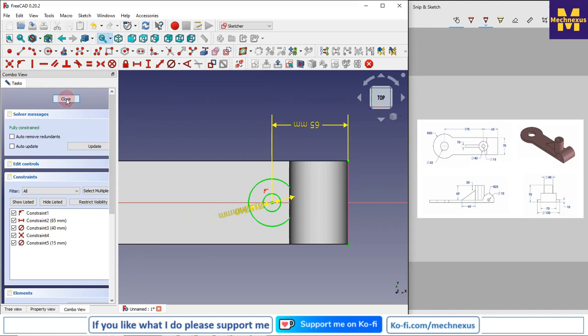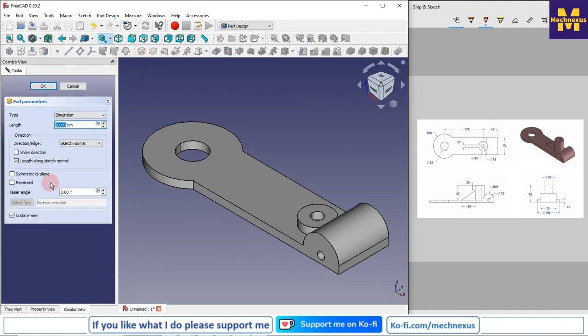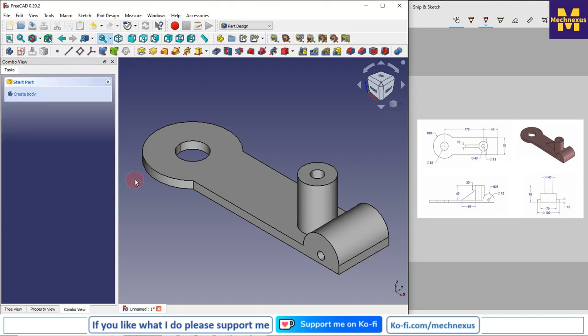Now I will close my sketch and now I will extrude it to the 60 mm length. So here I will go and say 60.